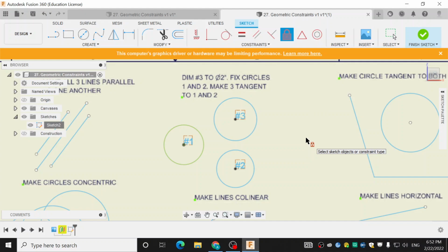This tells you that it's not dimensioned to anything. It doesn't have a position in space that we've given it dimensions to. Like, we don't know if we're X amount from the X axis and Y amount from the Y axis. It's just frozen in space, and that's why it's green. That's how you differentiate it from the standard black line, which is held in space because of its dimensions. So we're going to lock number 1, and then we're also going to lock number 2. When you're done, push escape, and 1 and 2 should both be green.